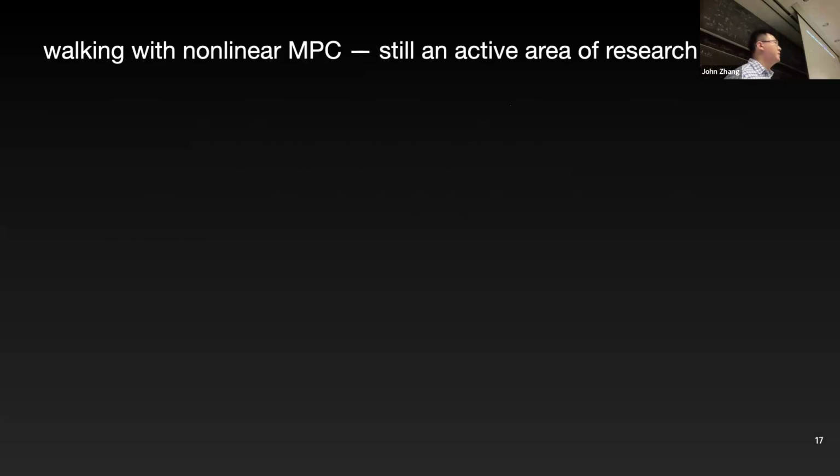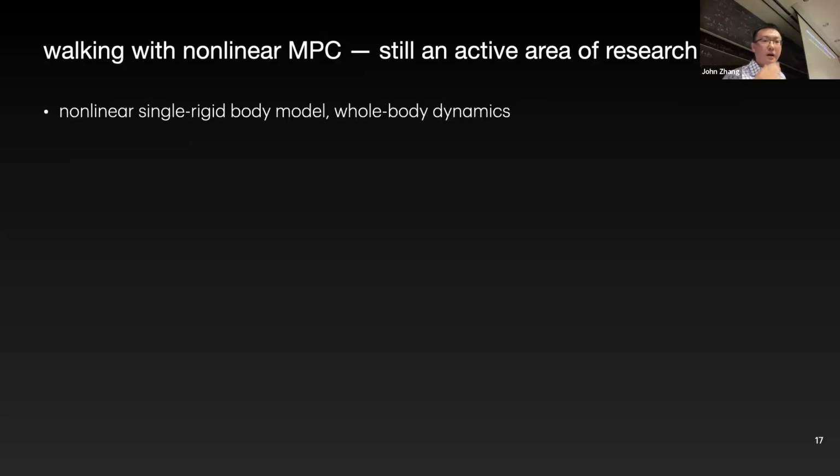But in general, nonlinear MPC is still an active area of research for legged robots. There are a bunch of things you can do here. You can do nonlinear single rigid body models, as we discussed a little earlier, or you can do whole body dynamics. It's still, in the general case, pretty computationally expensive. You have to do a bunch of factorization and linear algebra gymnastics to get these things to run in real time.